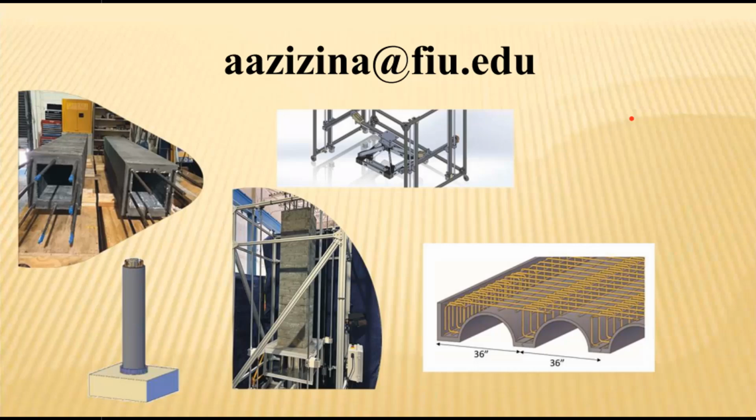Yep. Thanks, Paul. So how were these units cured? Obviously we moist cure and use different kinds of curing processes on these elements. Yeah, the ones we had in the lab, we did not cure. We just printed and then let them sit in the lab. We didn't have any curing compounds or anything, and we didn't see any cracking really. But it was in lab conditions with constant temperatures.